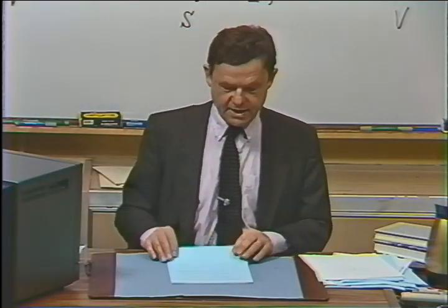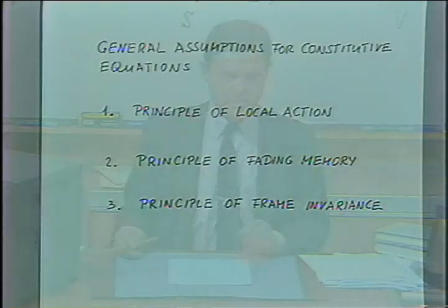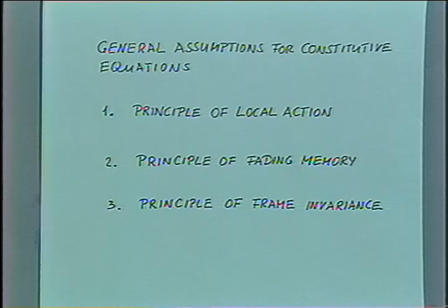Now, when writing constitutive equations, we have to introduce some general assumptions. We have to follow some rules. So when you make your guess, you want to formulate a relation between stress and strain, and then you have to follow those specific rules here. Three specific rules. The first one is the principle of local action.